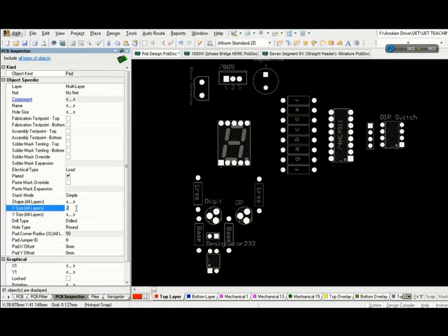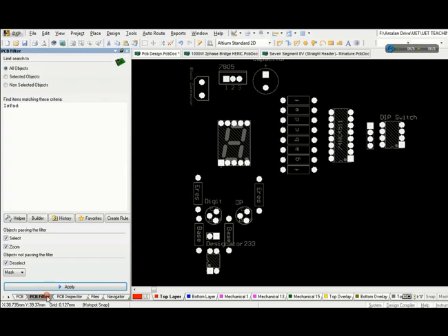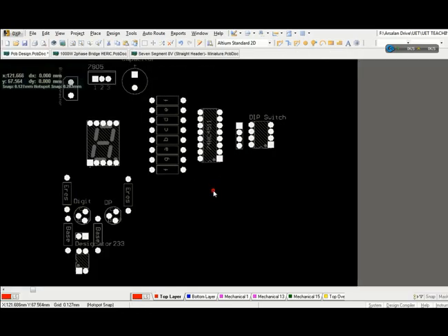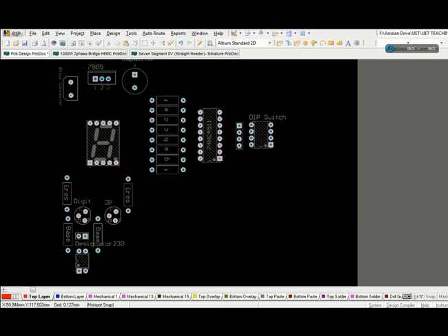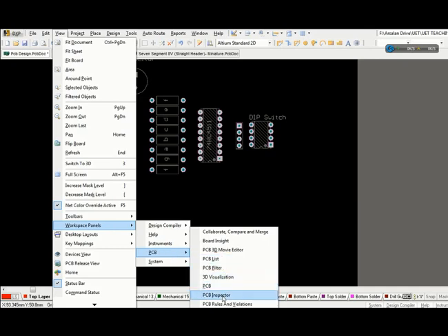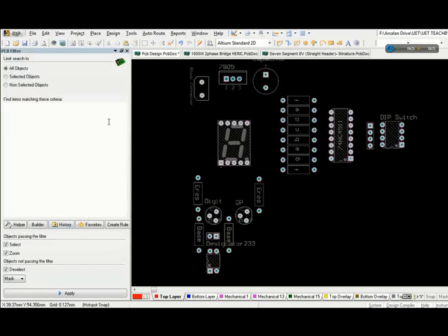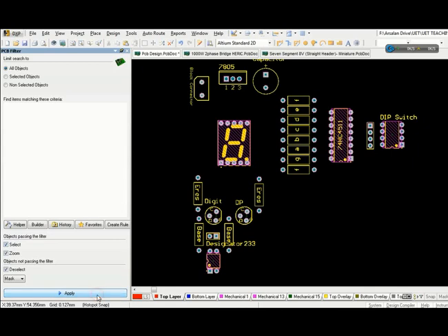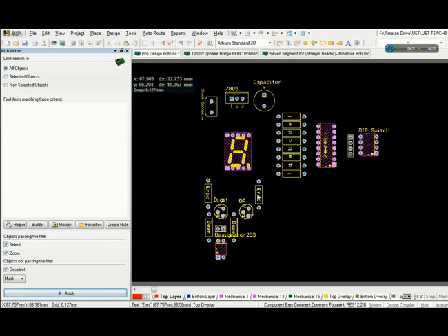And now I am doing it 2 mm here, and please use 2 mm as the standard size, at least up till the point when you are going to have all those practices done. Then afterwards, maybe when you will actually physically do PCB design yourself and then solder it, this is also a way how you can actually select from the view workspace panel PCB panels, and then you can select.